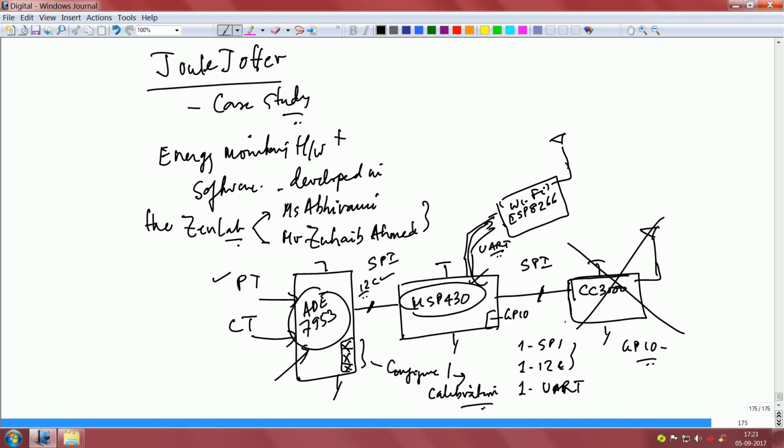Now I struck this off because this is a very early module from TI. They have improved versions of this chip, although we did not want to change anything. This was one of the first IoT Wi-Fi modules, and as the chip was not very stable, we had to apply a number of patches in order to ensure that it would work satisfactorily. Very soon it would hang. So communication between the gateway and this unit by itself was often a buggy situation.